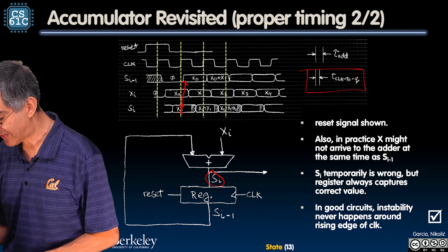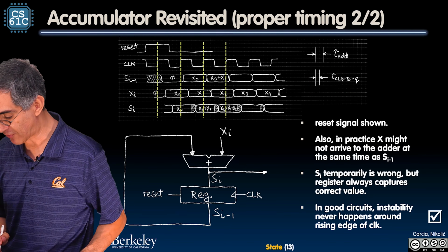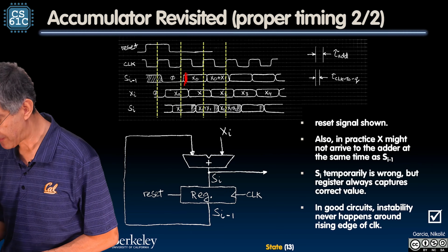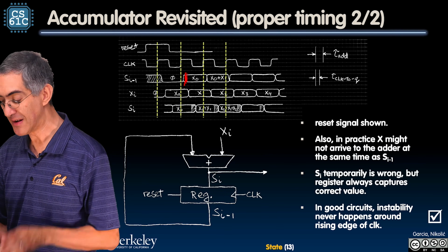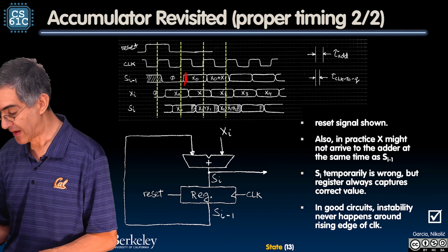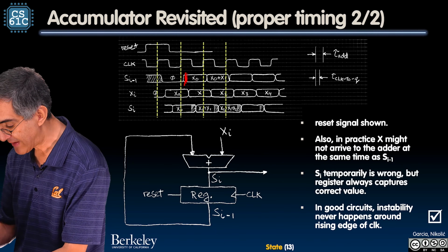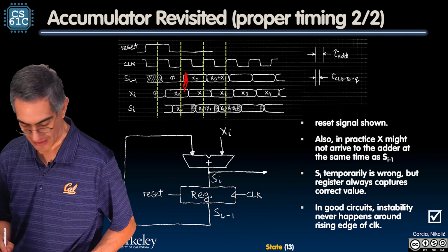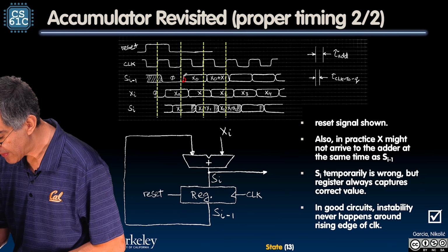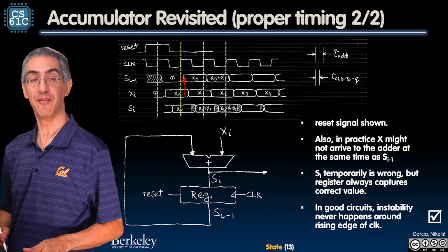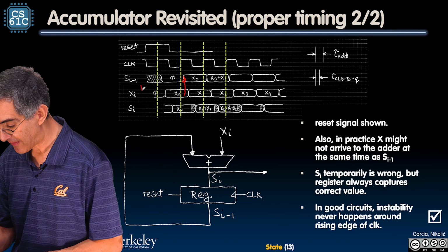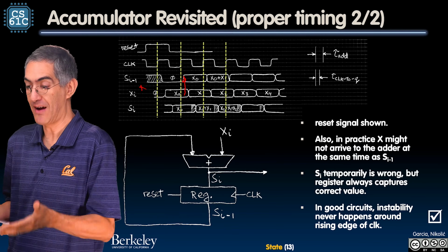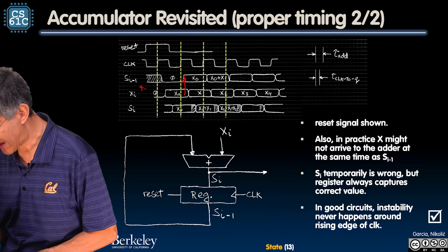So now I've got a stable X0. Now here's the part that's really interesting. There's my first value of S of I minus 1. X of I happens to be not synchronized with S of I minus 1. So now, watch this. This is crazy. Right here at this time, I'll try to zoom in here. So right there, I have what's on the input. This is the adder. The input of the adder, folks, is X of 0 and X of 0. I should never have 2 X of 0s in my output. And so watch what happens.